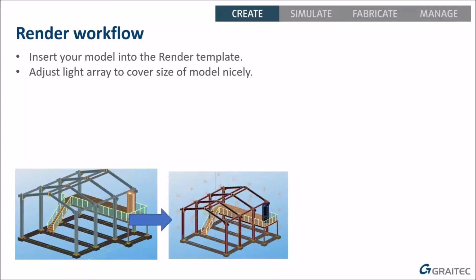I have found I can put a lot of light sources in. I did some big models for the competition. You were looking at the images at the start. I did a lot of models, and some of those are really quite big, and I put a lot of light sources in, but it didn't seem to affect performance too much. So you can get quite big. Don't get too carried away. You don't want every meter, hundreds and hundreds of them. But I did like maybe 25 by 16 at 4 meter intervals or something, and that would cover a big area. So you want to cover your whole model with lots of light.